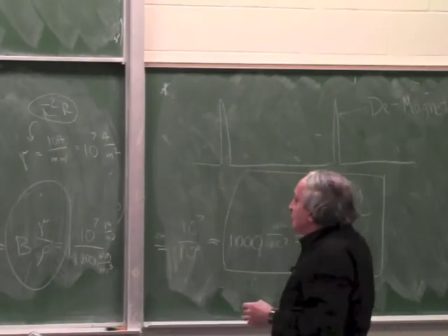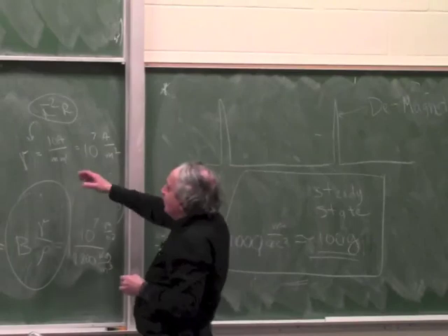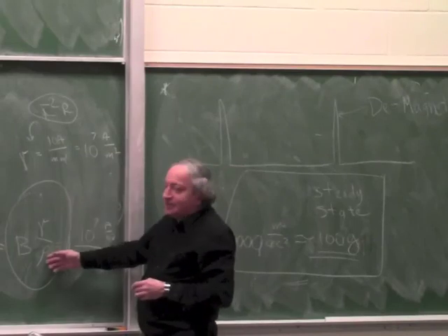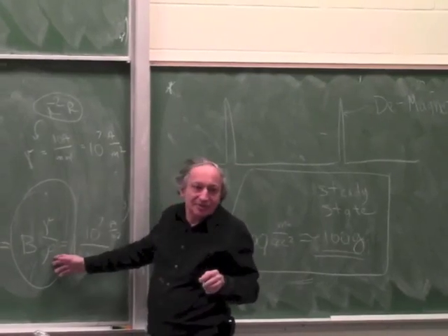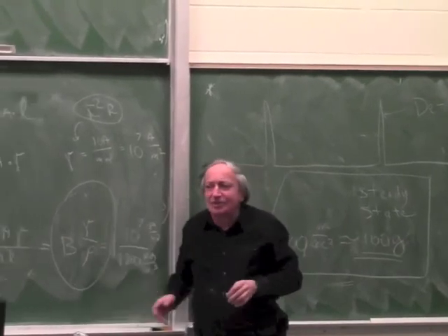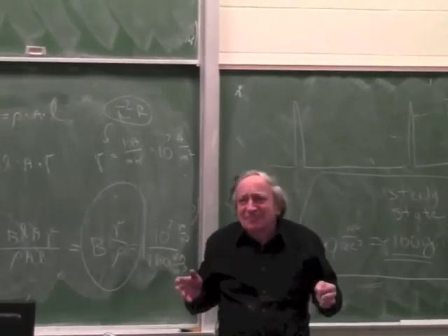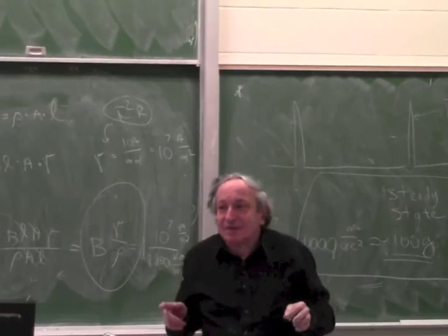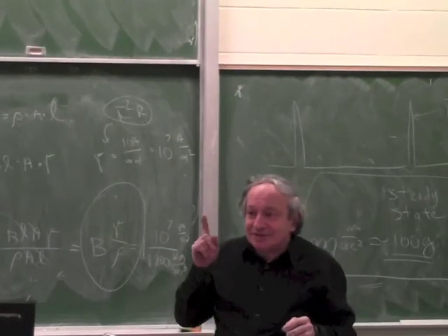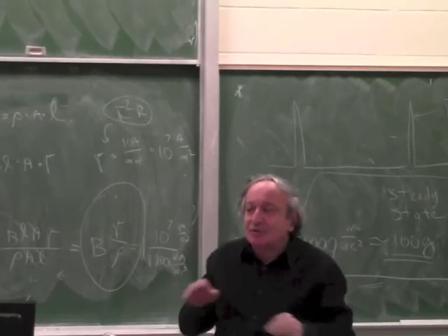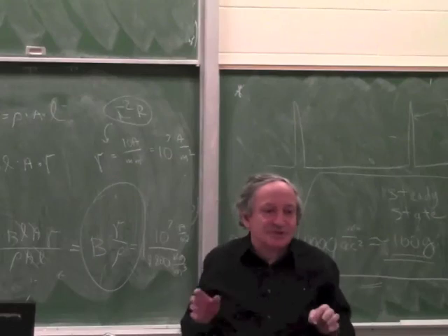Okay, so we can go to silver, but we only gain 10%. The density of silver is about the same as copper. So we can gain 10% going to silver, but it's a lot of trouble. It has been done though. At times where you need the utmost performance, you make the coils from silver.